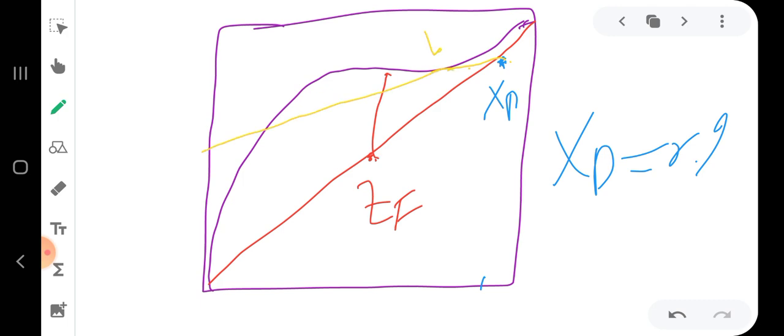Since it touched this equilibrium curve, I cannot go above it. So this line will determine the R minimum value. This line touched the equilibrium curve, even though it is not passing through the point where the Q line intersects the equilibrium curve.